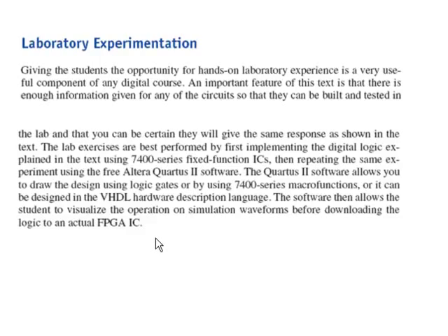Once you've built the circuit, you can also use Multisim, of course. A lot of times you'll design a circuit using Multisim at home, then you'll come in and build it up using the 7400 series integrated circuits, and then you could actually use Quartus to design the circuit and download it to a programming board.